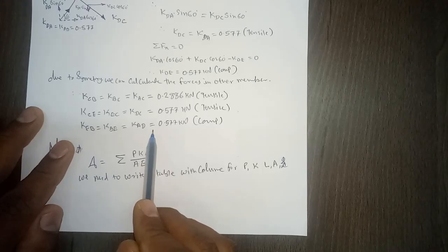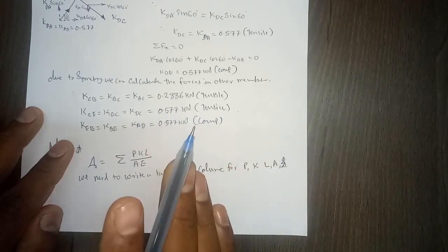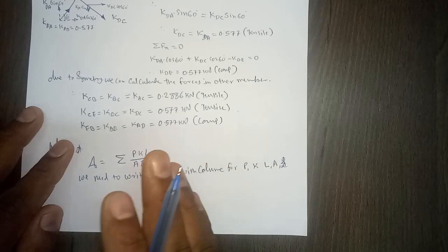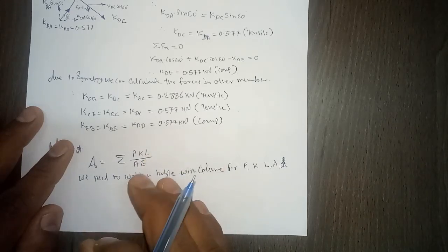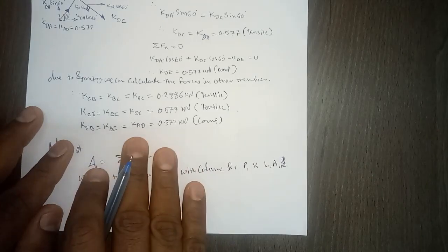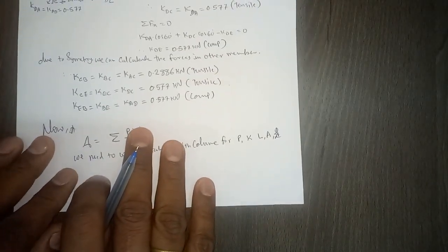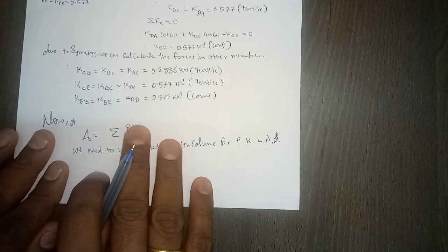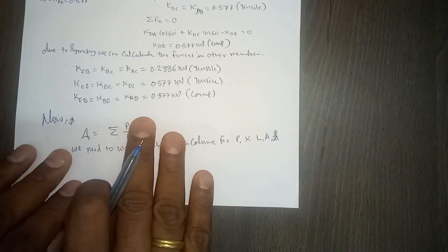Otherwise we need to calculate all these forces if your truss is not symmetric in geometry, or even if loads are not symmetric on the truss, right? But here, since the load and the geometry both are symmetric, we can directly write down these forces.